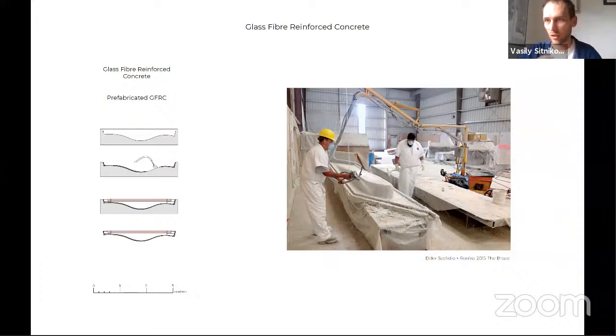At the same time, all those cast concrete elements impose a great dead load on the structure of the building. So there was always the intention to make it light, right? To reduce the mass of the structures and keep the free form geometry in the design. With these intentions, glass fiber reinforced concrete has gained very high popularity. Basically, having one digitally made formwork, one would just apply this very thick concrete, saturated with a very high content of fibers, by spraying on the formwork, which autonomously provides this very thin shell instead of a volumetric cast, right?